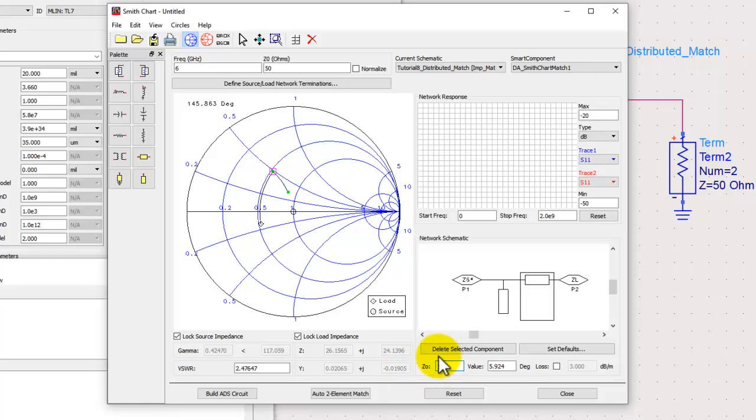So 105 ohm is the maximum impedance I can make. And now using that concept, I can go ahead and truncate this line. For this line, I just calculated the minimum I can go is around 24 ohm, so I will restrict myself to 24 ohm. All right. Now the rest of the fundamentals remain pretty much the same. So I insert a line. Now for this line, I need to modify the impedance to be 105 ohm, and then I can just proceed with the regular design.